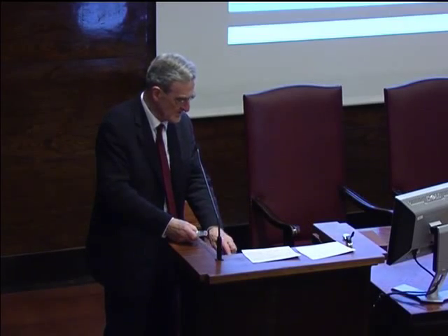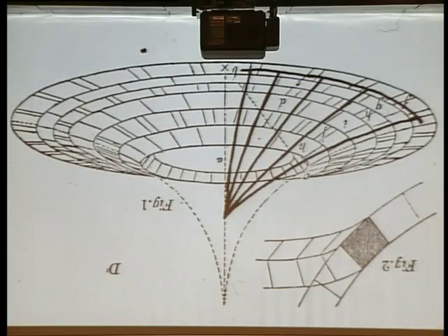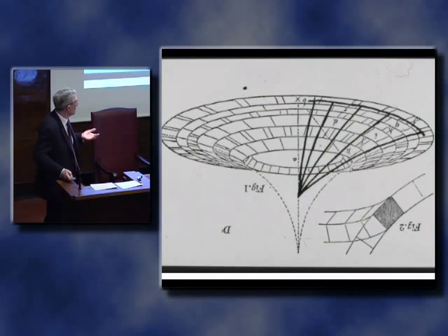Then if we turn that upside down, what we get is a picture of a sliced fan vault whose forces are concentrated compressively along lines like that, separated one from another so that there is no interaction between these solid lines there, and we can cut the whole vault in half there and throw this half away, and what we've got is just a picture, an analogy, a simplified version of the fan vault as it actually acts.